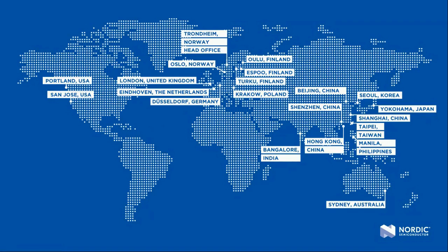Yeah, and then there is a question regarding iBasis and the lack of PSM sleep mode support for iBasis. So unfortunately, the situation today is that the big carriers limit some feature sets for the MVNOs in some parts of the world. So this is something that you should also go and push iBasis on to try and improve. We are also working closely with iBasis and the big carriers to try and make them open up to also support sleep modes with virtual operators. But if evaluating and using PSM is very important for you and you don't have support with iBasis, our current advice is that you get a local SIM card.